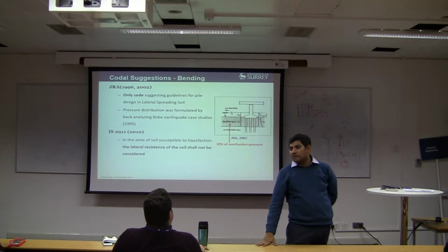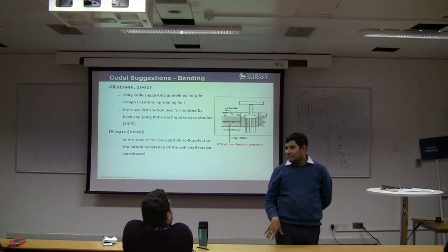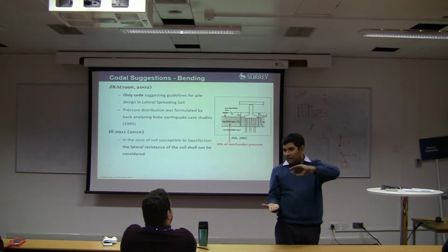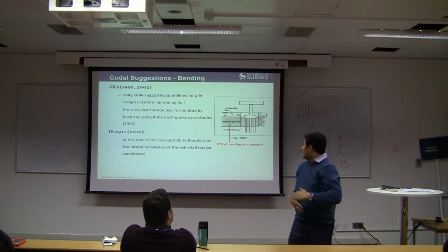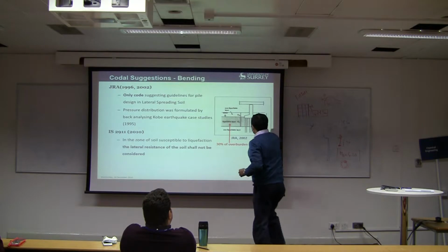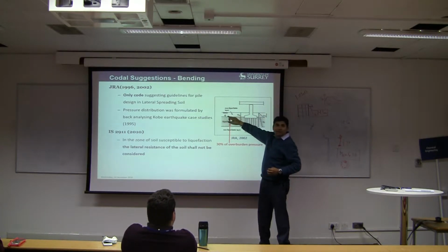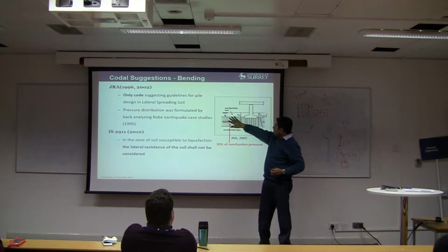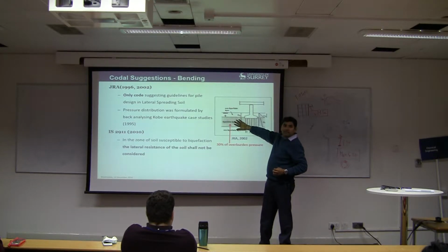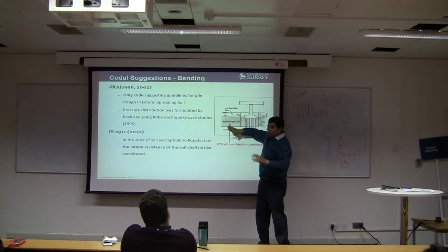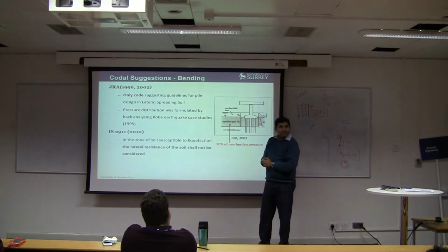Therefore, the important part is where is the water table? In a river bed, the whole thing can liquefy, but in normal ground, you will have a non-liquefied crust. If the water table is here, this part will liquefy, this will not. So if this liquefies and wants to flow, it will take the top with it, right?